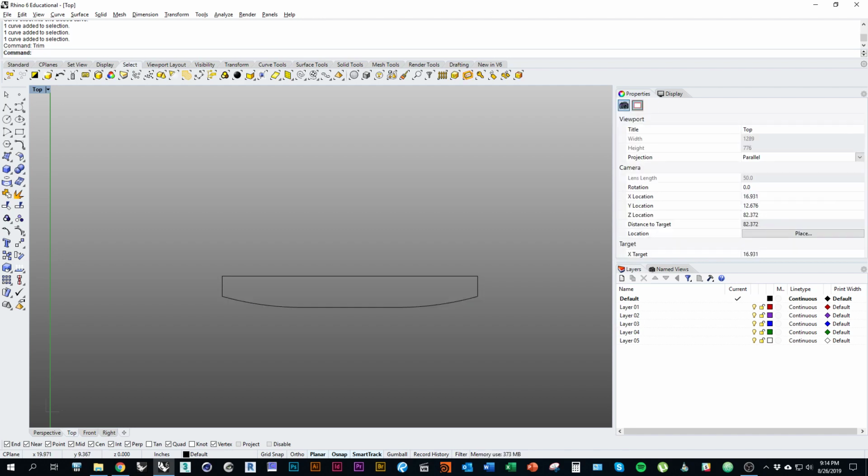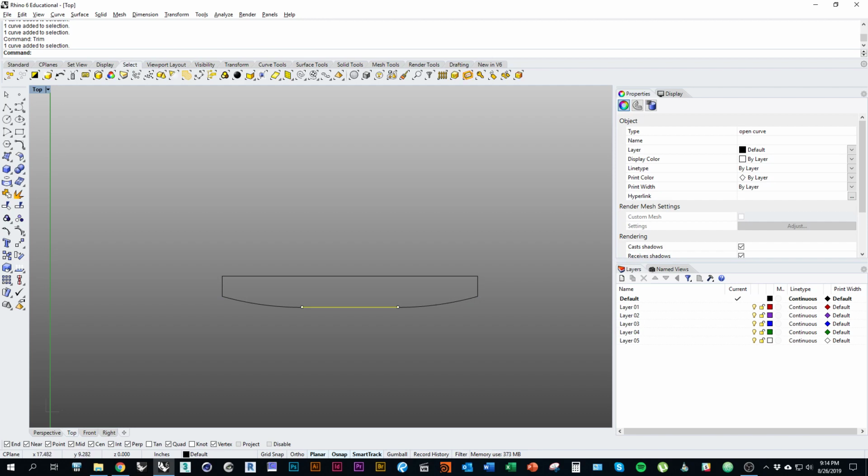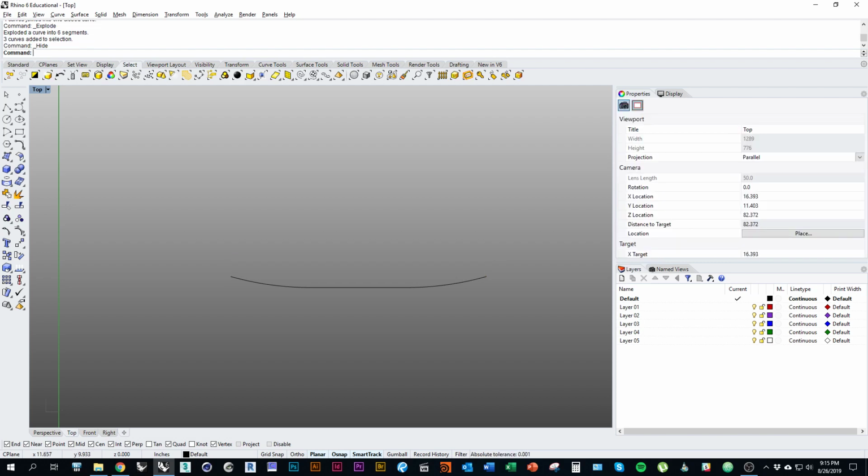So now when you click on this flat line, you should only see one pop up. If you have two, make sure you go ahead and delete one of them. Okay, and that's essentially it. So I'm going to select all those lines and join them. And this would actually be the profile that we would go ahead and print out if we were making the wood seat. And like I said, if you were making the metal seat, you would just have this profile line at 15 inches.